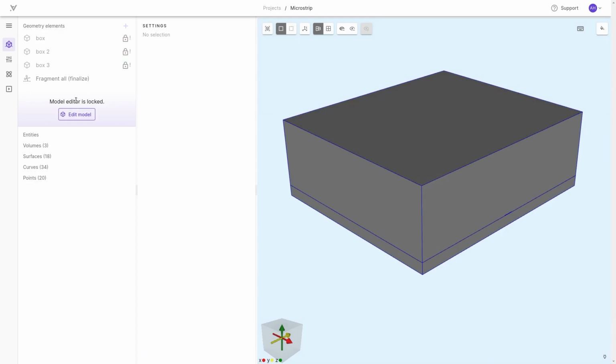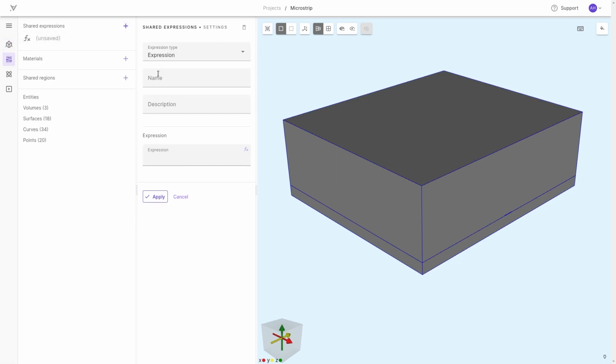It's worth noting at this point that you could parameterize the geometry. So instead of typing this, you could have used shared expressions. For example, if you would define capital W as being the width of the conductive track, you could use capital W in the geometrical operation to parameterize your geometry. Here, I will use this kind of tools to define my frequency with a default frequency value of 5 gigahertz, but I will override it by doing a frequency sweep in the simulation. But now the system knows FREC, and it knows that it's 5E9 by default.